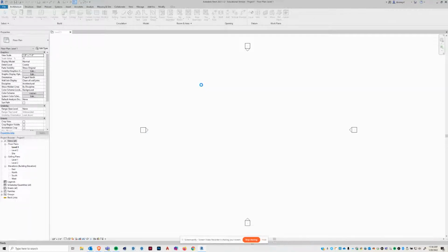So it's saved on my desktop, and if you look up at this top text line here, it tells you what Revit version you're using, as well as the file here. Okay, so let's start by creating some grid lines, some grid datum lines.